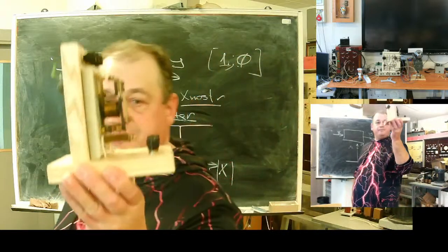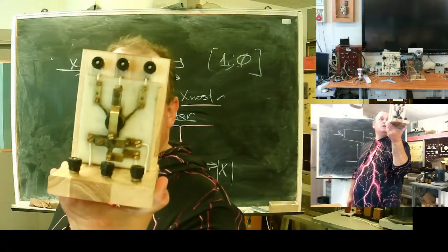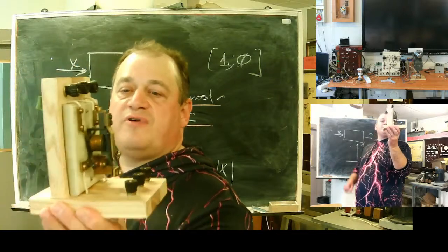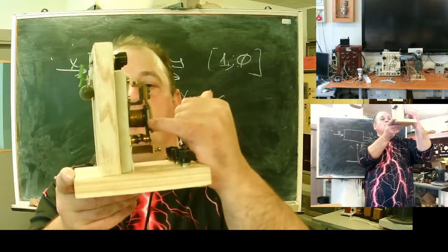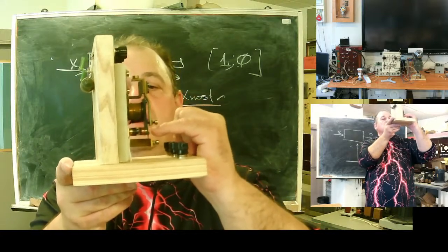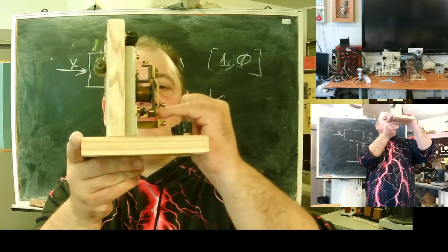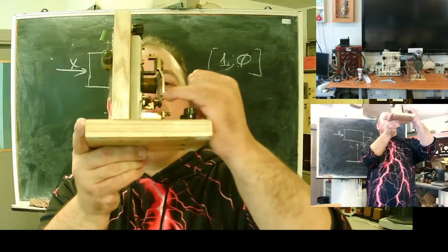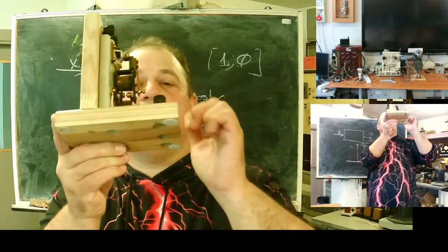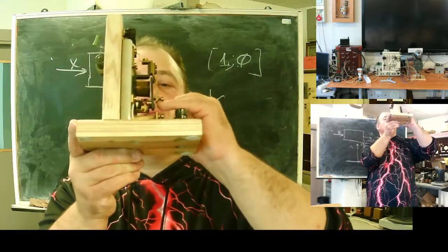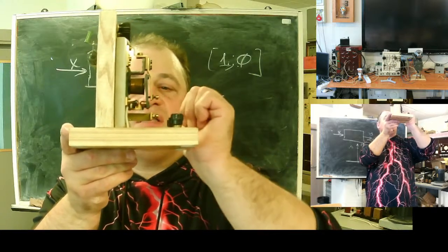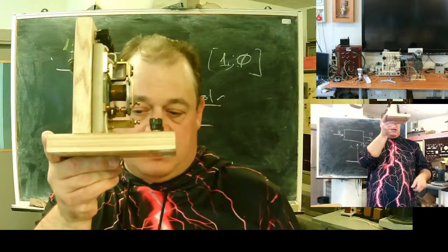Look what I have. Old, it's a kind of telegraph relay. Here I have a coil. If current flows, it has two groups of contacts. One is make, normally open, you see this large couple contact. And also here the small one, hope you can see them. This tiny one, service contact, normally closed, they open.